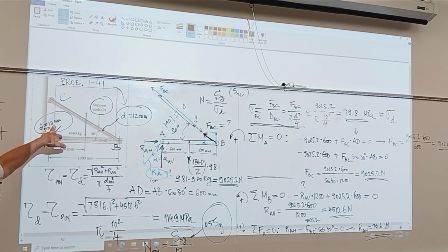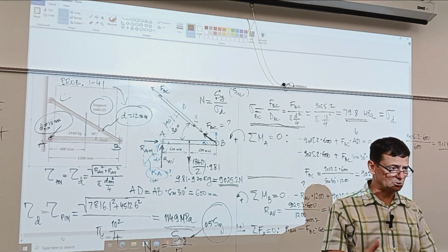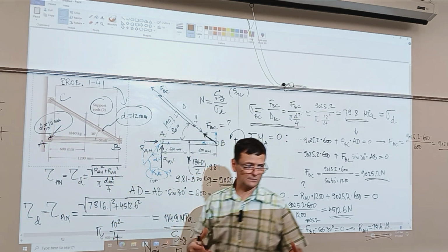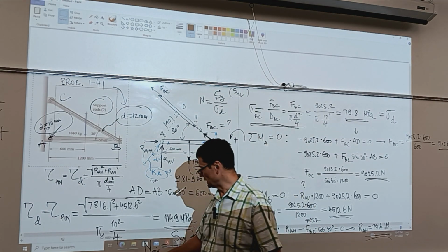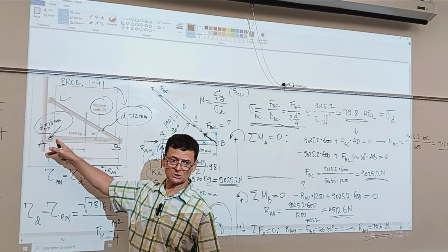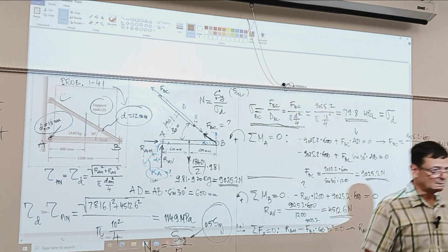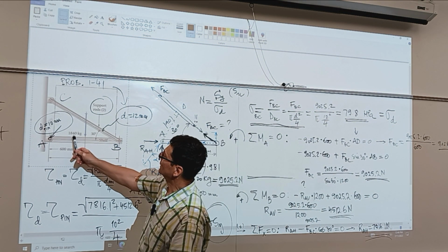So what do you need to do? Go back to the pin and increase its size. It might need to be a full 20 millimeter diameter. And this is what design engineers do. One approach is to just do repeated analysis. You pick something based on your experience, your flair, you run the numbers, and it says it's not okay. I need to go back and make changes at the pin. Or maybe you just rate the shelf for less load. Check with the customer: do they really need to put an automobile there?